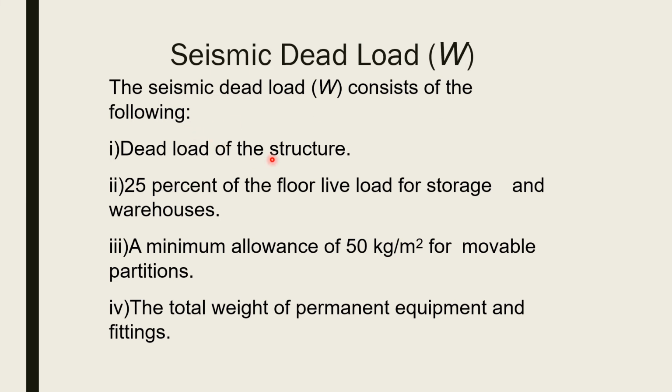First, the dead load of the structure, meaning beams, columns, slabs, all types of dead load of the structure, will be included in the seismic dead load. Second, 25% of the floor live load for storage and warehouses, where you are going to store your bags of food, wheat, rice, etc. For warehouses, you have to consider 25% of the live load.